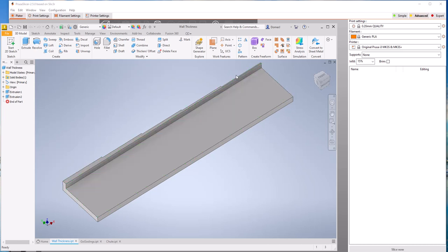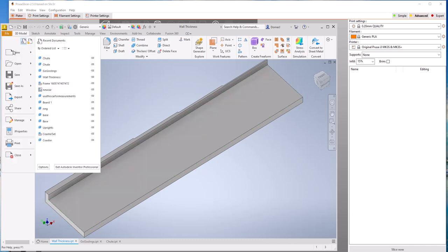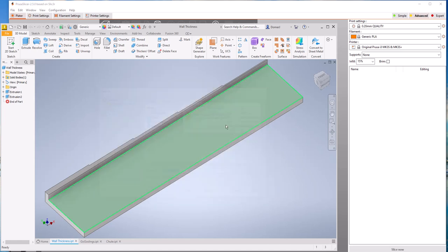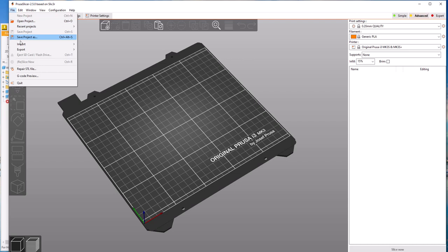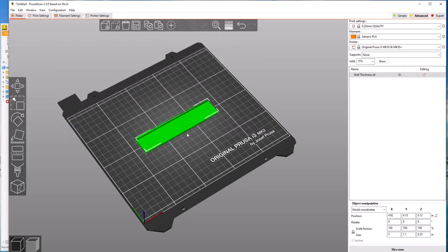I've designed these wall thicknesses here to be 0.02 thick, 0.04, 0.06, 0.08, and 0.1 thick. And then we've got about a 1/8 inch floor down here. So we're going to export that file from CAD as an STL so that we can bring that into Prusa, import that file, wall thickness, and it brought that file in.